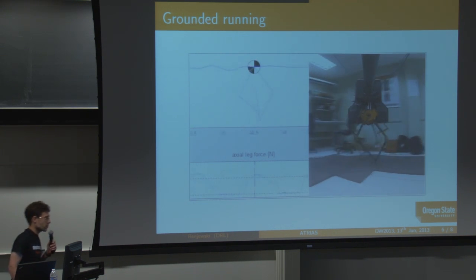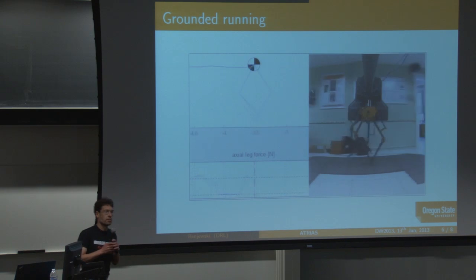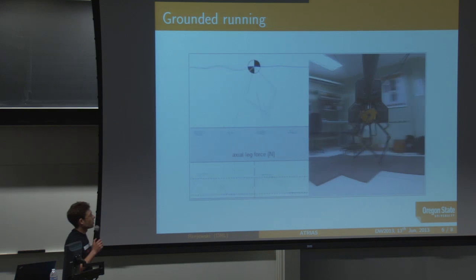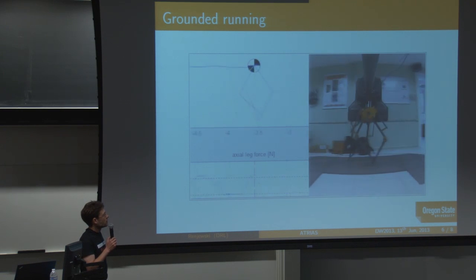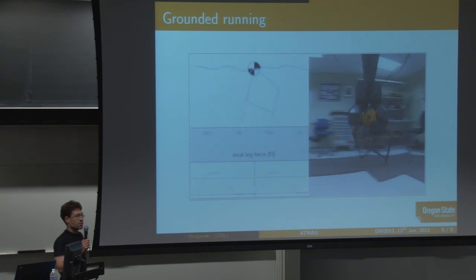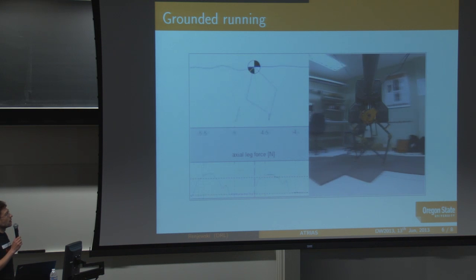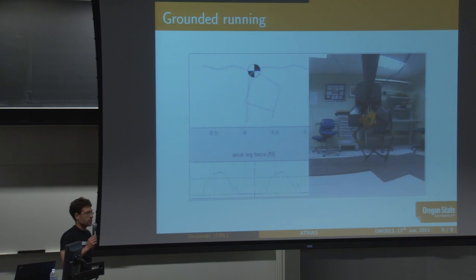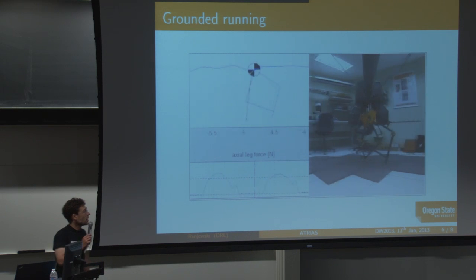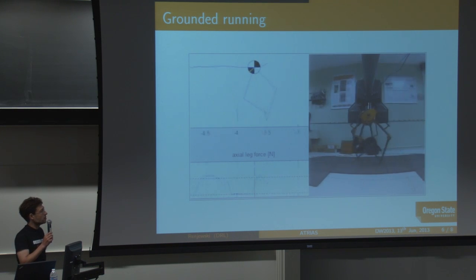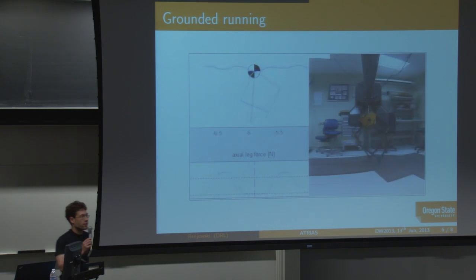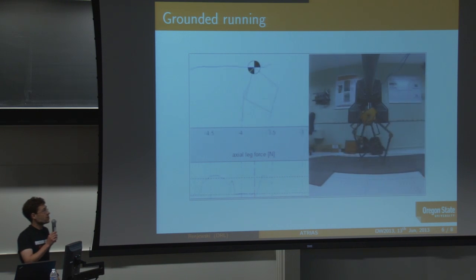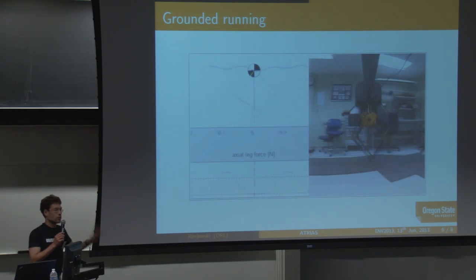Okay, so just some numbers on that gait. We stored about 260 joules in each spring. We walked at 0.7 meters per second, and what we have currently is cost of transport electrically about 1, and mechanically between 0.15 and 0.4. I have to mention that the torso is still locked to the boom, so that is our next step.